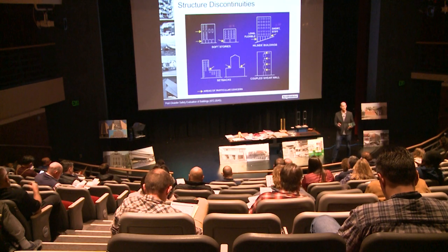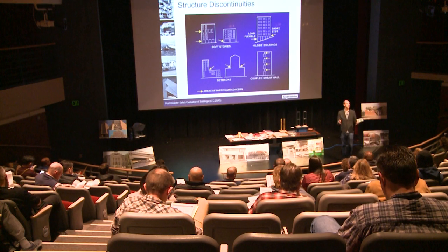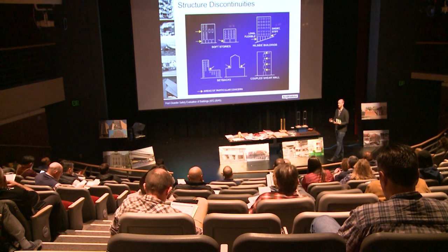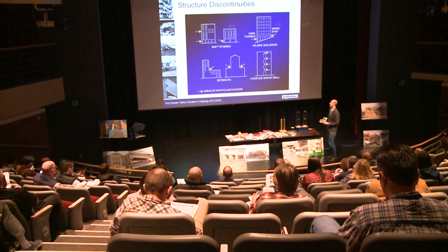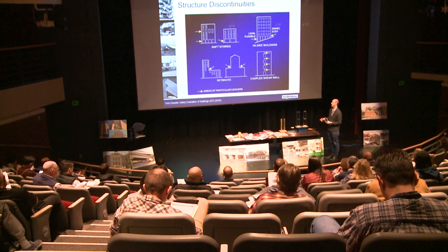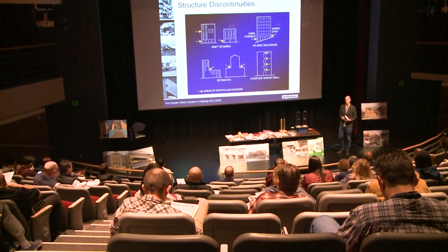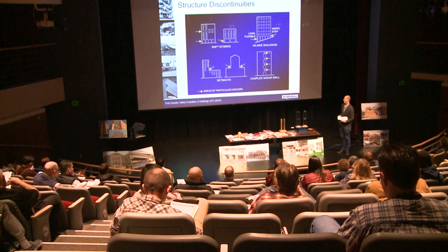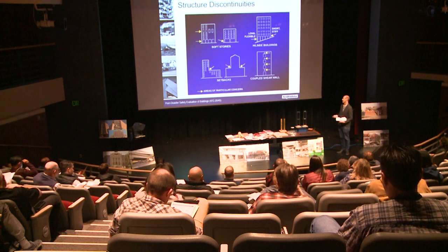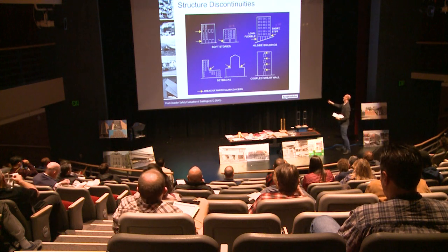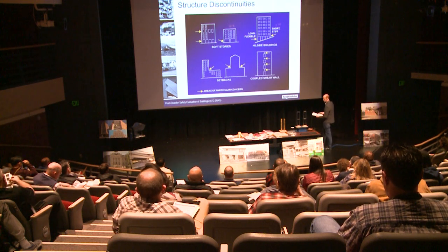The exception to that would be concrete core wall buildings, a lot of high-rise. You have one concrete core wall we talked about earlier around the elevators, and that's less accessible. But in many examples we have today, you can see the coupled shear wall buildings and the concentration of damage there, the vertical setbacks like we were just talking about, and the dynamics of two different natural periods interfacing right at that setback elevation, soft stories, and hillside buildings.